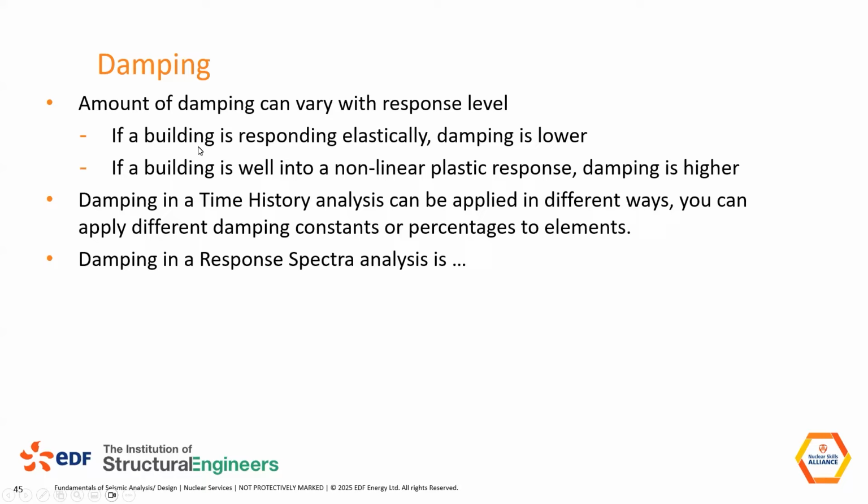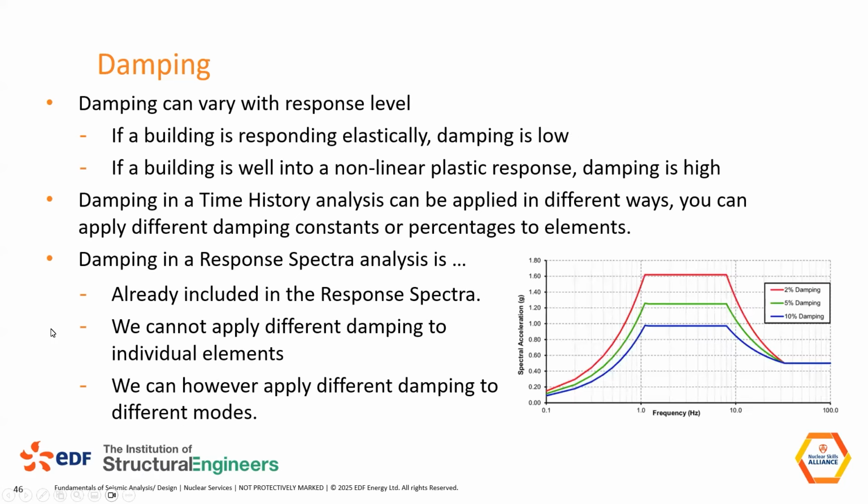So, okay, I've said this already. Damping is lower for elastic and higher for nonlinear. In time history, you can apply damping directly to elements. In a response spectrum, hopefully you remember this from when we talked about it, the damping is already included in the spectra. So when you generated a spectra, a response of a system, you chose a damping level.